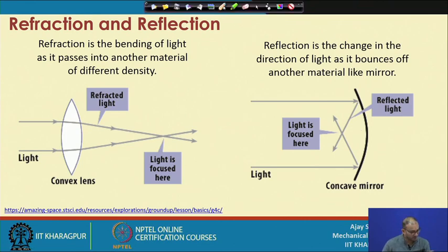Similar to what we have discussed here, if there is roughness here and the shape is not exactly concave, that means there is no figure accuracy, then this ray will come here and go to this location, another ray coming here will go here, this ray will go here. So, you will not get this particular focus point, and that focus point is very important, because sometimes you want to concentrate your whole energy at one location to get things done. There are different material science applications and different microscopic imaging applications, where you want to focus the light at one location only.